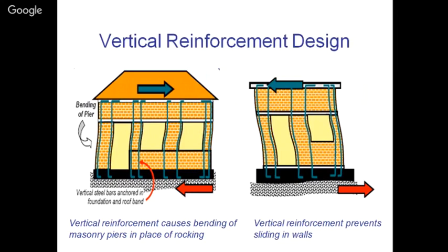These all can be safeguarded against earthquake forces if we are going to use horizontal bands along with our vertical reinforced masonry. So vertical reinforcement which is being provided here is shown in the figure. We can simply provide this vertical reinforcement using hollow block masonry, where a slot is there in the masonry through which this vertical reinforcement passes, and we just confine this masonry, these reinforcement bars with the epoxy or simply with the cement slurry or with the cement paste or cement sand constituents.